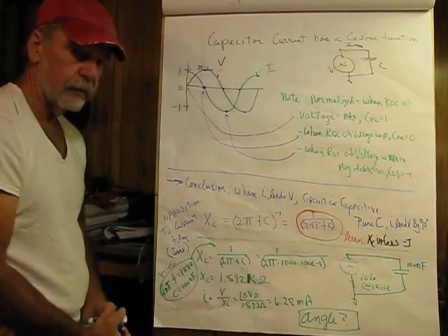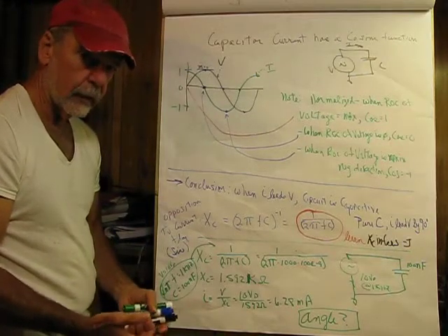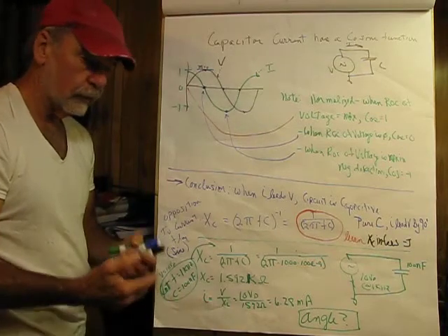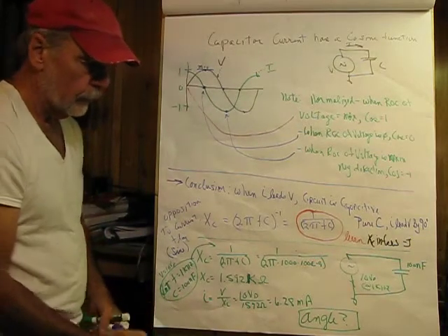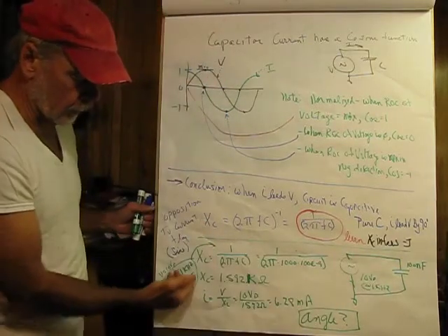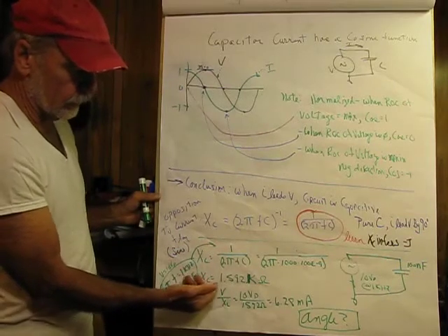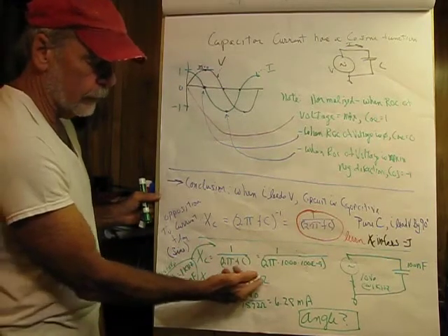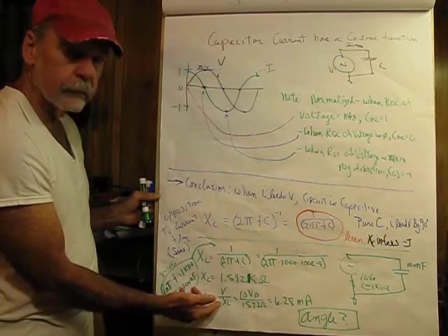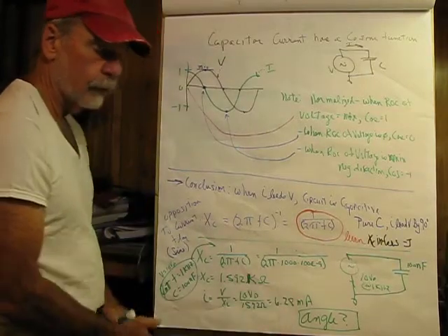So you have to be comfortable with entering values in engineering notation, highly preferred over scientific notation. It will save you from making mistakes. So here's our circuit here. Then it's just a question of voltage law, Ohm's law. So capacitive reactance for these values comes out to be 1.592 kiloohms, and the current flow equals V over X sub C, and that comes out to be 6.28 milliamperes.